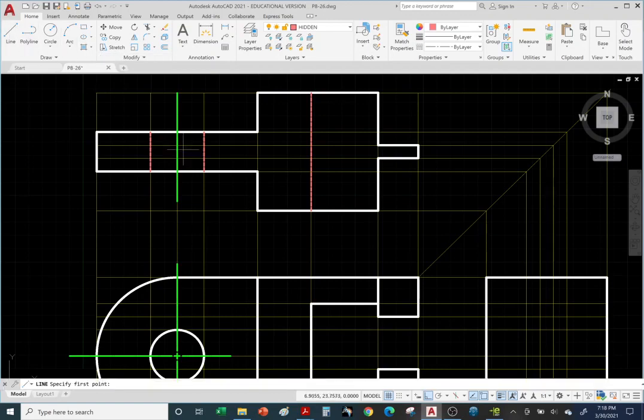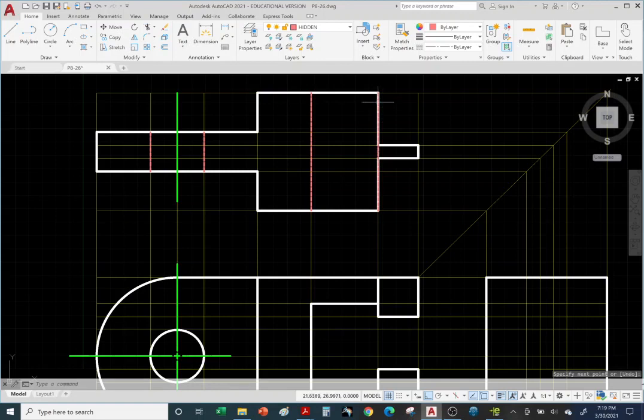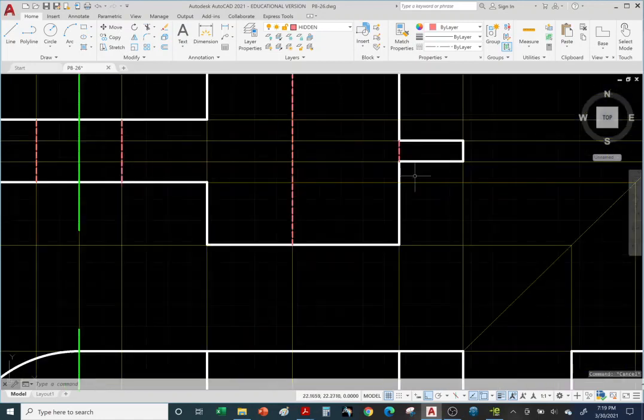So we're going to draw a red hidden line. Again, it's representing the edge here. If you were to draw the red hidden line going all the way across, it's not necessary because it's overwritten by the white, thicker, visible object line. So we're going to go ahead and just shorten it. And there it is. Hit Escape. Zoom in. There it is. There's the red hidden line.